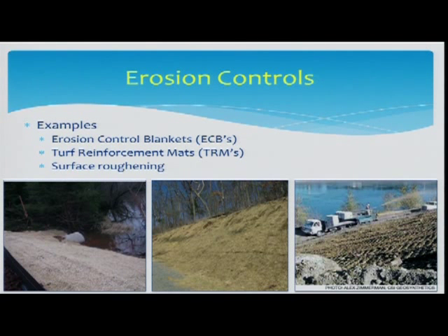Different types of erosion controls that you can use besides leaving it undisturbed until you need to. There are erosion control blankets available where you just unroll the stuff out there, and it's got straw in a net mesh fabric. Turf reinforcement mats look like silt fence basically, but it's big rolls or mats of it, and you can tie that in, and it can take some amazing, boy, the word just escaped me, Dr. Vogel, shear stresses. Yeah, thank you. It can really withstand a lot of that. You can lay that out in the bottoms of channels and things.